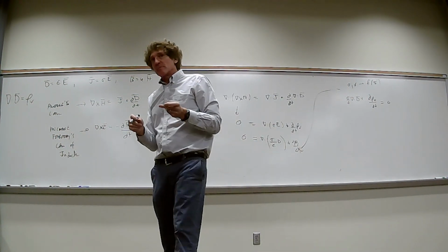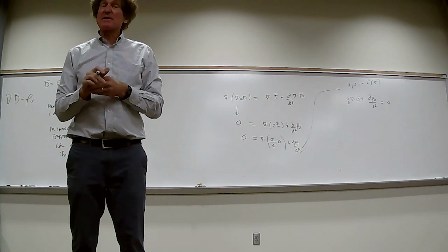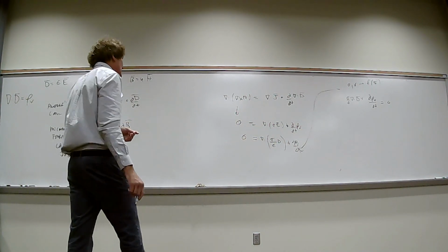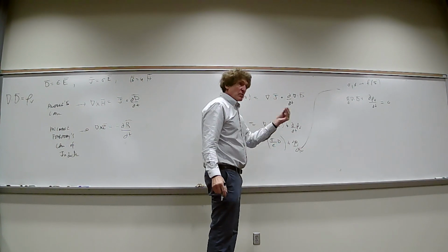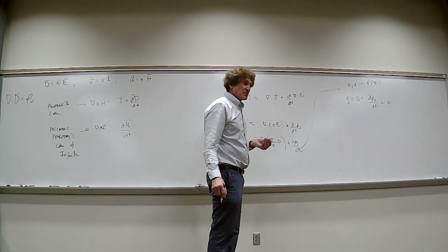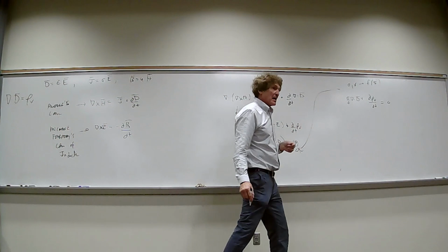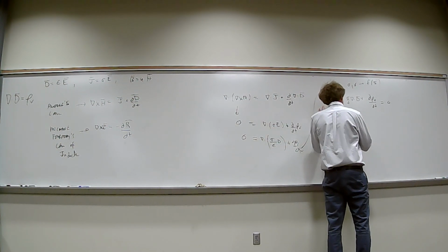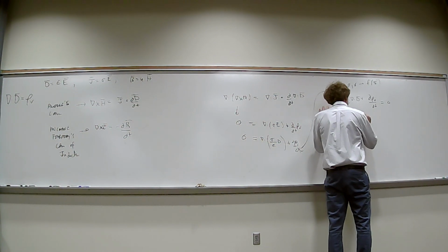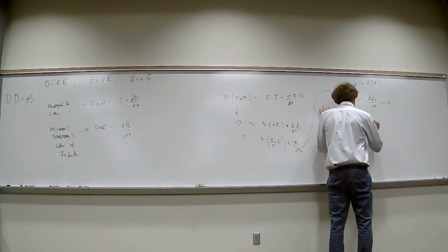I simply pull sigma and epsilon out in front because I'm saying they don't spatially vary. If they did spatially vary, then this divergence equation would require additional operations. You'd have other derivatives. But I'm saying they're constant. What is that? That's rho V. So I have sigma over epsilon rho V plus d rho V dt equals 0.